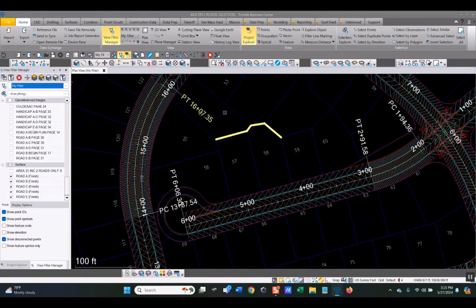Now, this piece of text wasn't totally inside, but part of it, when you're picking a piece of text, it doesn't have to be fully enclosed. Just as part or piece of it touches the window, it's going to grab that. But when I am selecting objects, lines, line strings, circles, doesn't make any difference. You normally, if you're going to do it with a mouse, you have to pick and create a window, and that window or rectangle has to be fully encompassing that entity.